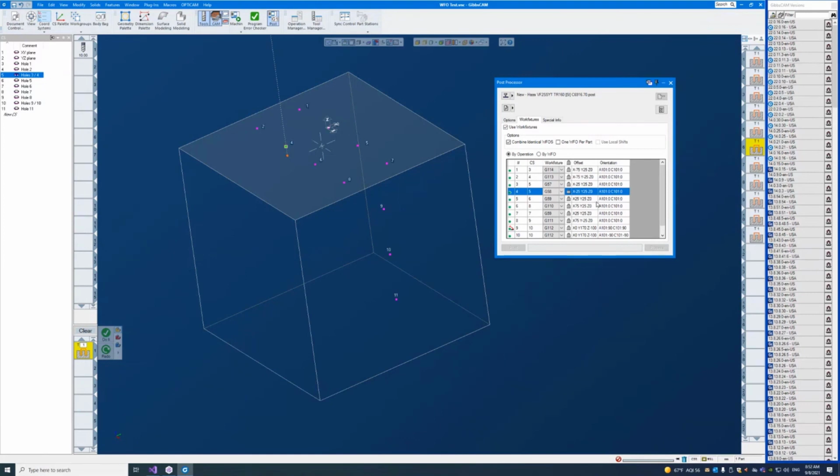I've also proposed a way to reserve a range of WFOs. Renumbering them is great. That's a great start, and it's something that was really hard to do before we had this feature. But ultimately, the reason a lot of people want that is because they have multiple parts that are left set up on a particular machine, and what they really want to do is blacklist a set of work fixtures and tell us, you can assign the work fixtures automatically, but please don't use these ones.